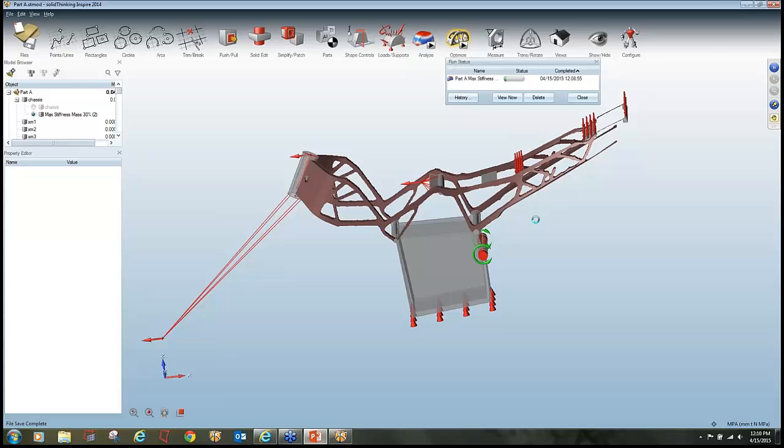So my actual baseline analysis results for the stresses are 148, and now I'm performing the analysis on this shape and will check the results. If it's more than 30%, I will change the shape somewhat and then perform the analysis again.